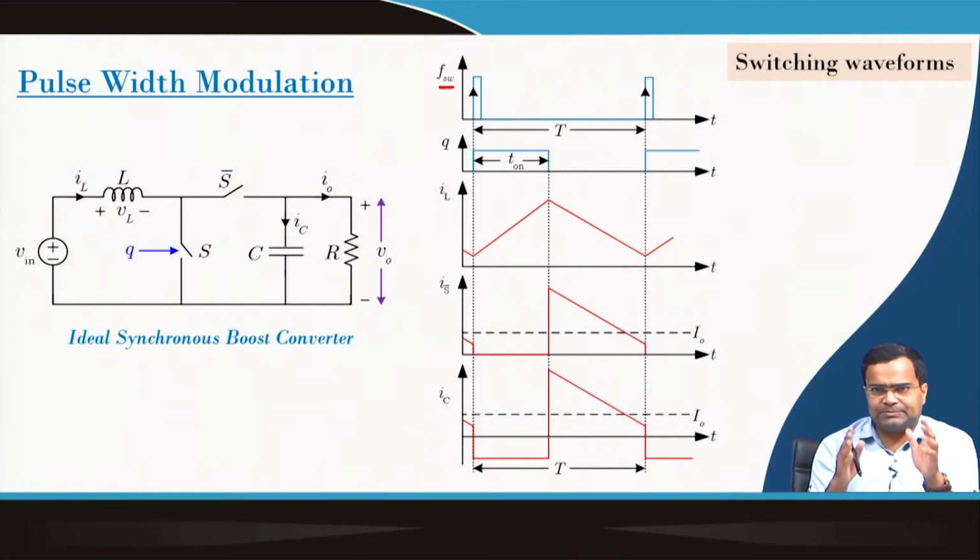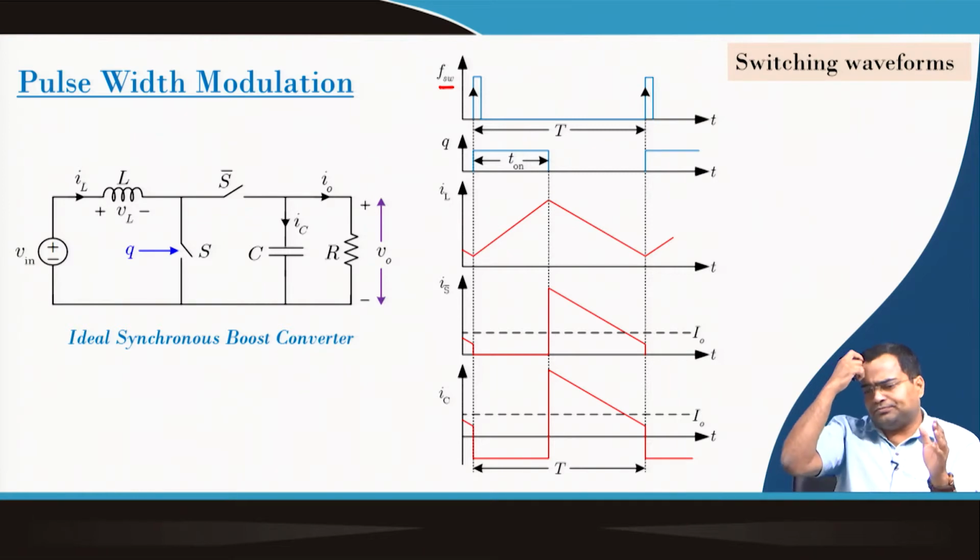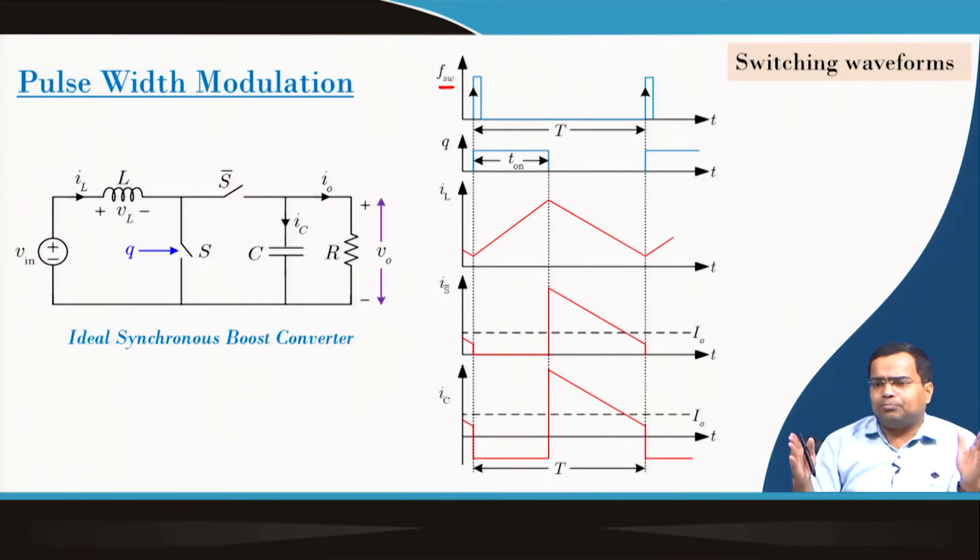Okay. So, the clock is a fixed switching frequency clock, but we can program this frequency according to our requirement, provided that it satisfies the design constraints of the converter, because when you design a converter we need to know the switching frequency, or we need to set some switching frequency. Accordingly we design the inductor, capacitor and all this.